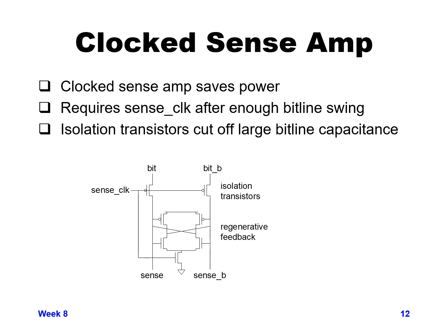Then when the clock goes high, in effect, the pull down will be turned on, and the NMOS and PMOS back-to-back inverter that's shown there will detect which side is lower than the other and will help pull that side lower quicker than the other side.